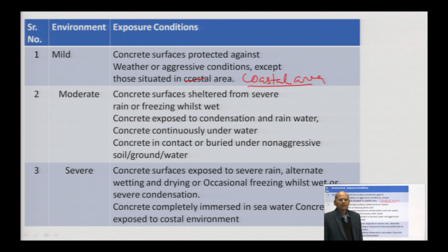So, what is moderate? Concrete surface sheltered from severe rain or freezing, while wet concrete exposed to condensation and rainwater, concrete continuously under water, concrete in contact with or buried under non-aggressive soil, ground or water. That condition you can consider a moderate condition.